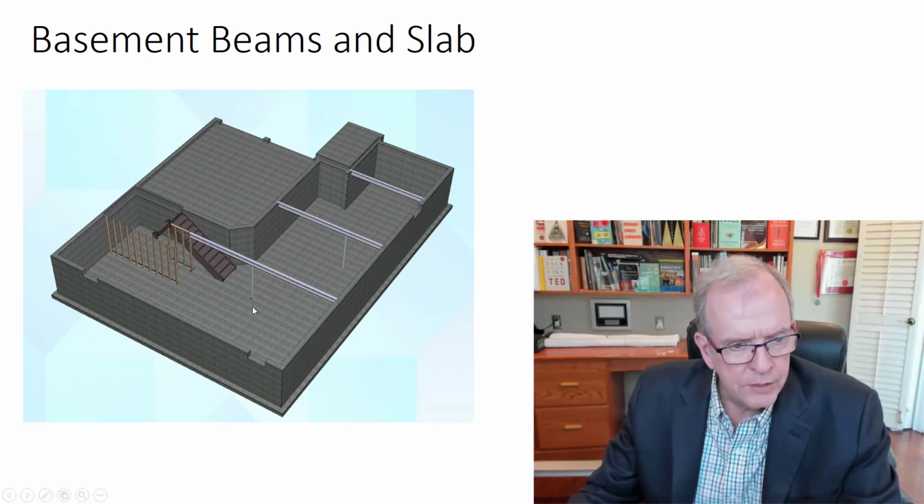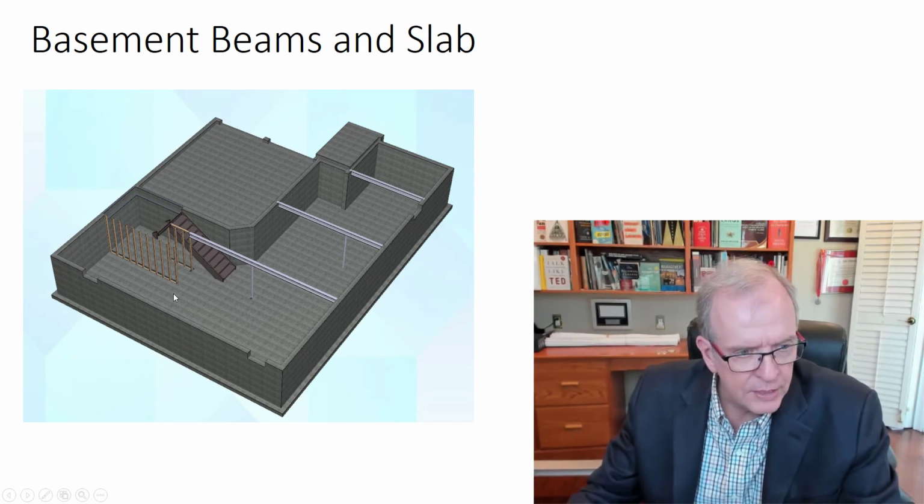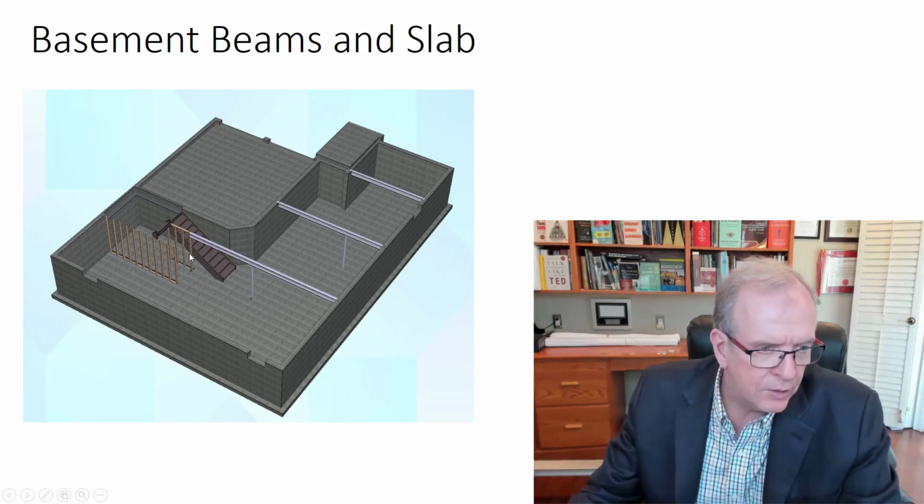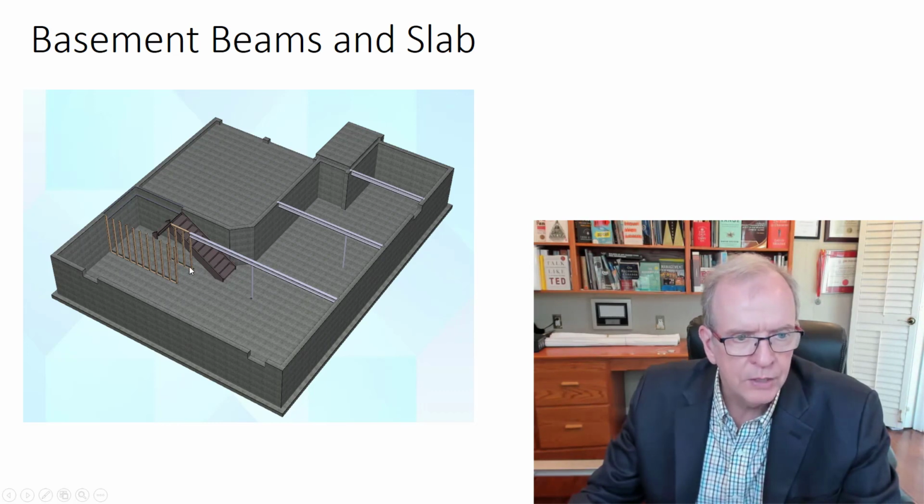So the footings are underneath here that we just talked about, and underneath here, remember that teed one, that strip footing here for the wall, and so you need to have that in place so that you can then put your wide flange I-beams across, and they're dropped into pockets so that it's actually sitting on the concrete foundation walls. The builder in this particular case, it shows wood and it says that on the drawings, but it was much easier to keep it with steel, so they kept it with steel on both.